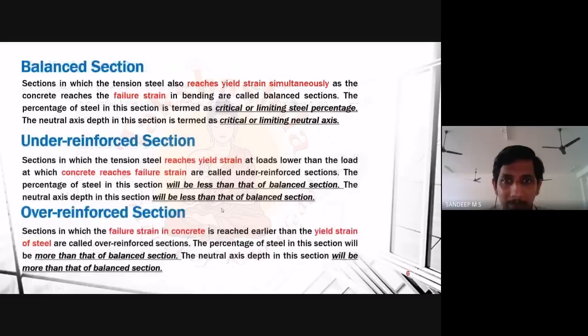So these are the main things that you should note when you explain about balance section, under reinforced section and over reinforced section. In balance section, again I am repeating, the yield strain, not the failure. Please note, during your examination, please don't write that the failure of steel or failure of concrete will occur first. That is actually not correct. The material is not failing. Only thing is that in the case of balance section, it is a section in which the tension steel reaches yield strain simultaneously as the concrete reaches the failure strain. Both are the same thing. So please try to explain in this way in terms of yield strain and failure strain.